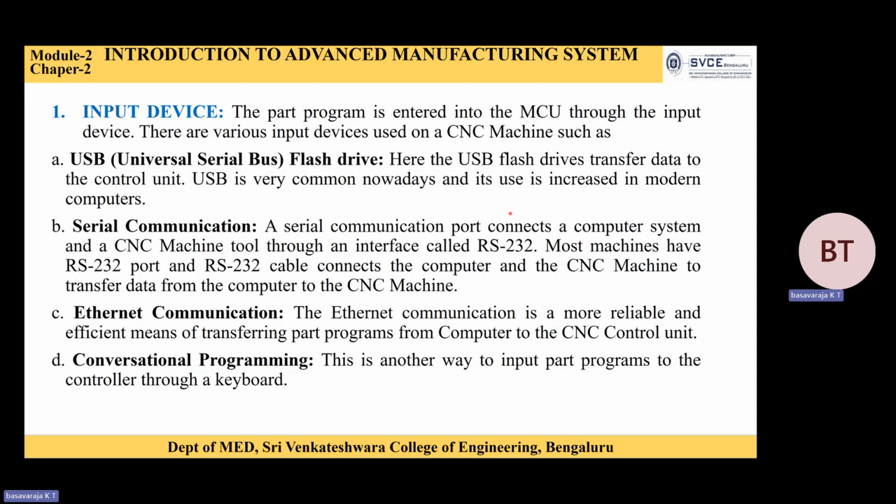Most machines have an RS232 port, and the RS232 cable connects the computer and the CNC machine to transfer the data from the computer to the CNC machine, where it is stored in the CNC main memory.